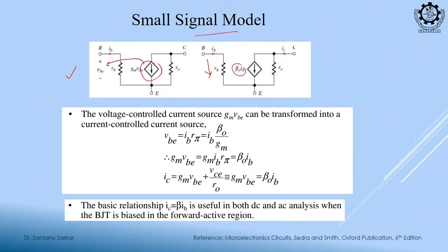NPN transistor. So far we are discussing NPN, right? We are discussing the NPN bipolar junction transistor. So, this is a model, I am again telling you, this is not the real circuit, this is a model of the behavior at which signal? AC signal. The amplitude of this AC signal should be large or small? Small. Why small? So that it remains in the active region, the linear amplification range is satisfied.